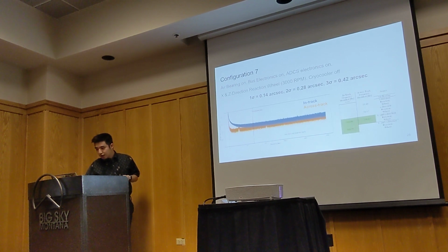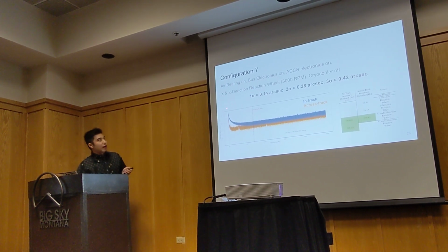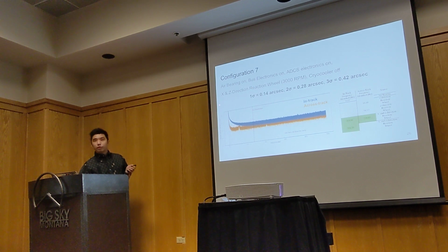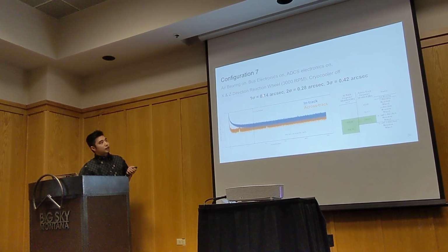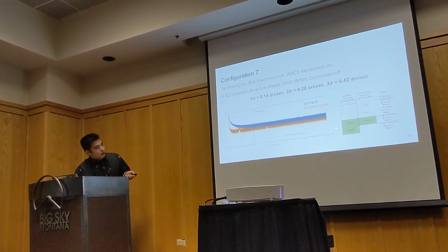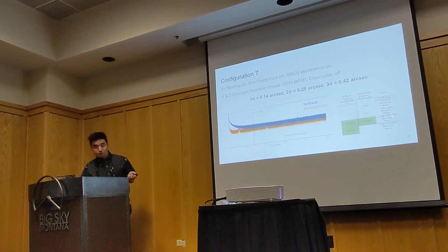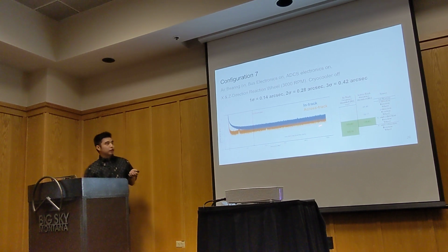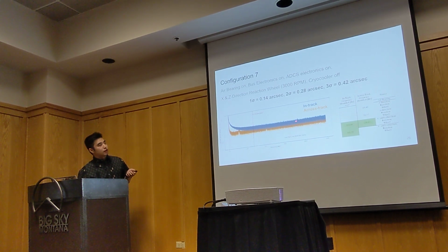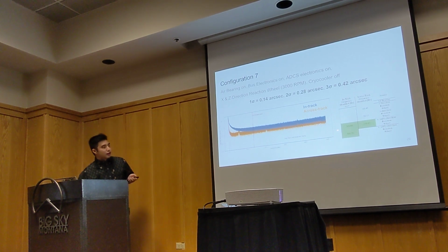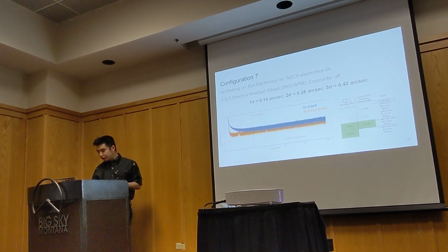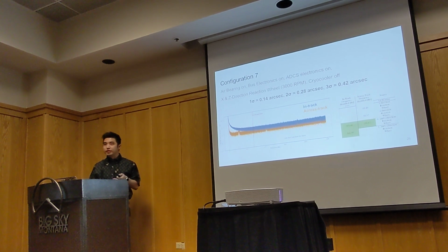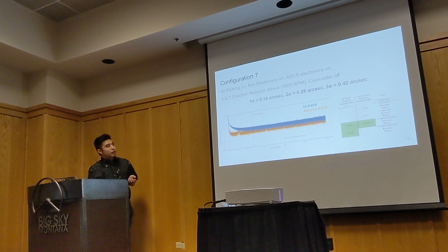the jitter values. And so finally, and I think the most interesting configuration that we were able to test, we run both the direction reaction wheels, and now you can see that the jitter values remain about the same, but we introduced some new frequencies here, at 210 and about 368 hertz. This 210 hertz occurs in both the in-track and the across-track direction, and this 368 hertz occurs in the in-track direction. This was really interesting because it demonstrated the non-superposition of these jitter sources, and how testing an integrated system like this is really beneficial.